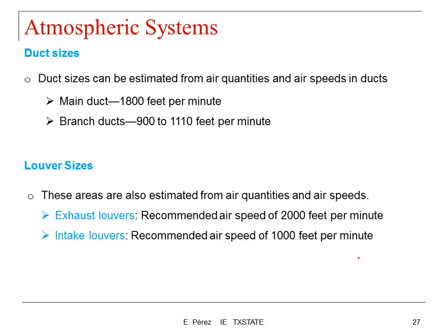So again, the important thing about these systems is that it's going to occupy some area of your facility, so you need to be sure where to place the equipment and also be aware of the area that it's going to occupy. Some other things to take into account are the duct sizes. Duct sizes can be estimated from air quantities and air speeds in ducts.